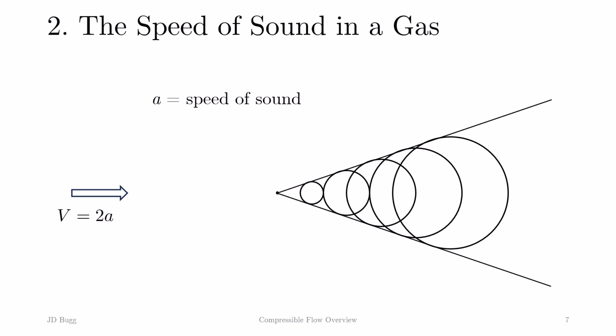If we happen to be located out here in this region, anywhere outside of that cone, we do not hear that source. Remember, this source is stationary, and if we're stationary, standing out here, and the wind is just blowing by, we will never hear that thing. This is called the zone of silence. If we are located inside the cone, we would certainly hear the sound. This is called the zone of information.